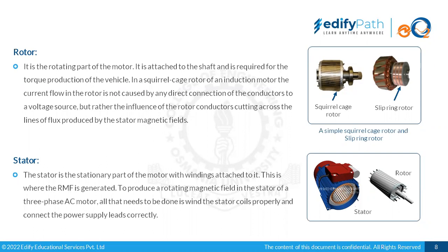So if we talk about a three-phase induction motor, the windings will be placed accordingly, so that when connected with the source, the rotating magnetic field would flow through these windings placed in proper ratio. The proper coil ratio would be maintained. The number of slots would be fixed, and they would be placed in such a way